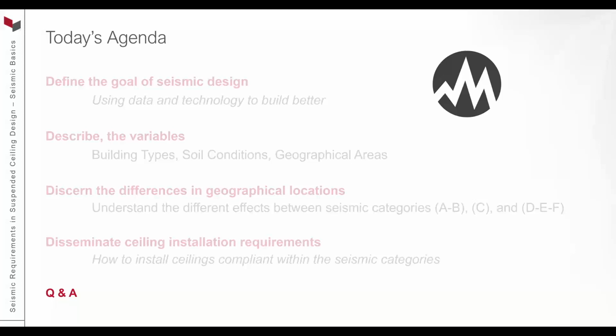So each one of those areas of depth, and we at USG, I actually have an engineering report that shows from 2 foot all the way up to 17 feet, I believe, what those gauge materials are and the shapes and sizes of the metal studs that are used. So they vary based on plenum depth and seismic criteria.